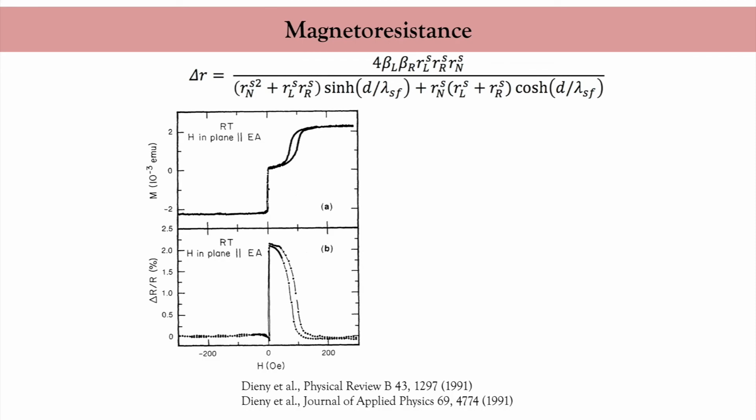One of the nickel iron layers is pinned by an iron manganese antiferromagnet through exchange bias, so it has a larger coercivity than the other nickel iron layer. Therefore, by starting from large negative magnetic field, the magnetizations of both nickel iron layers are parallel to each other, pointing downwards. Then, by decreasing the field magnitude and changing its sign, the layer with the lowest coercivity switches first. Finally, by further increasing the magnetic field, the layer with the largest coercivity switches, and we obtain a parallel configuration,